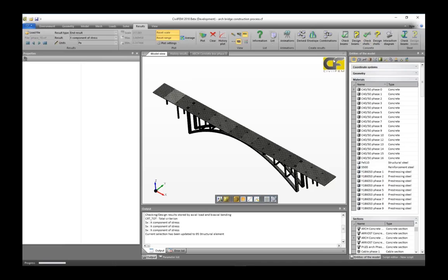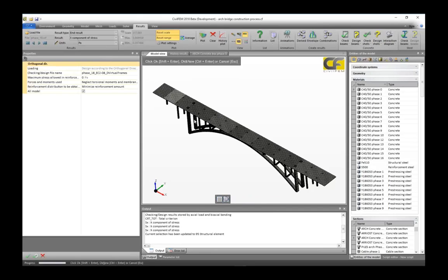Well, in this case, what we are doing is designing instead of checking design cells. So we are doing design by the orthogonal direction method, with the normal directions in X and Y, normal and longitudinal of the decks. Here we have different options to neglect torsional and membrane forces. We are going to consider, for the bending plus axial, also the torsional and in-plane shear. So we are going to calculate reinforcement considering axial plus bending plus in-plane shear plus torsional moment.